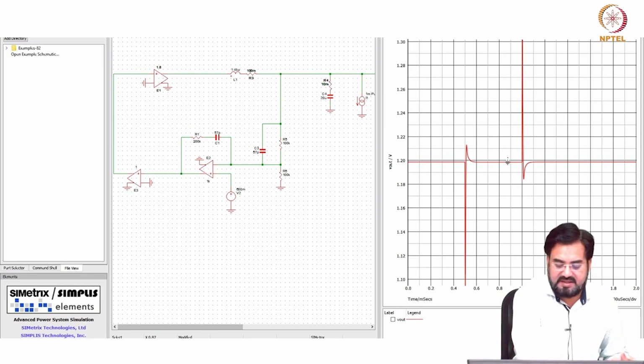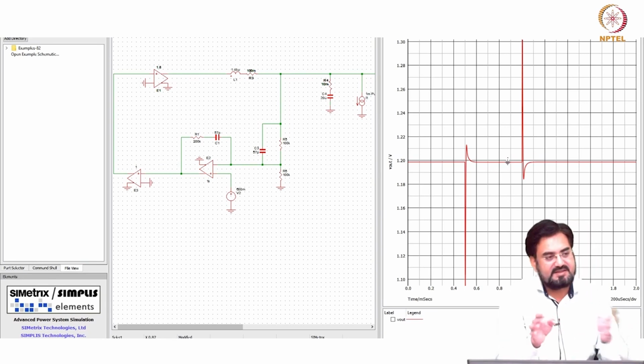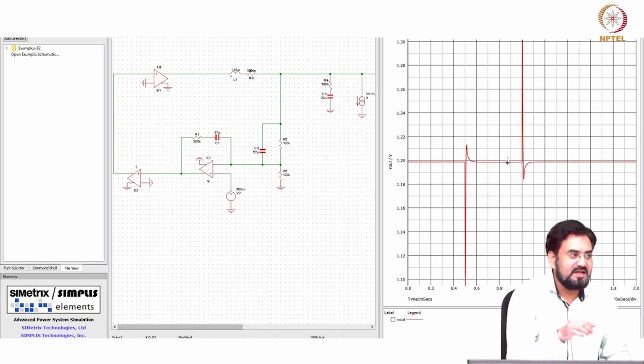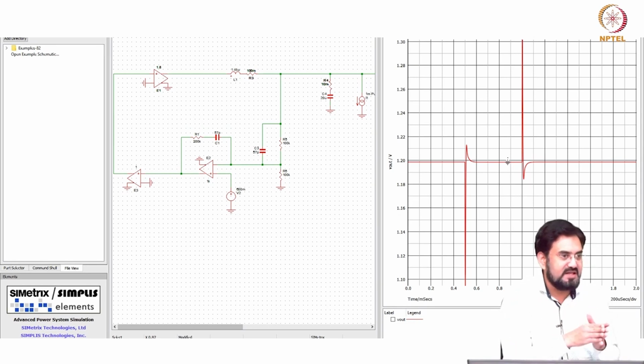No, phase margin is fine, you will get phase margin because Q is reduced. But let us say then you adjust everything, you adjust the zero and you get the same phase margin. What about transient response? You do not remember? Transient response should improve because your slew rate will be higher for that current. So when you change the duty cycle, your current in the inductor can change faster.